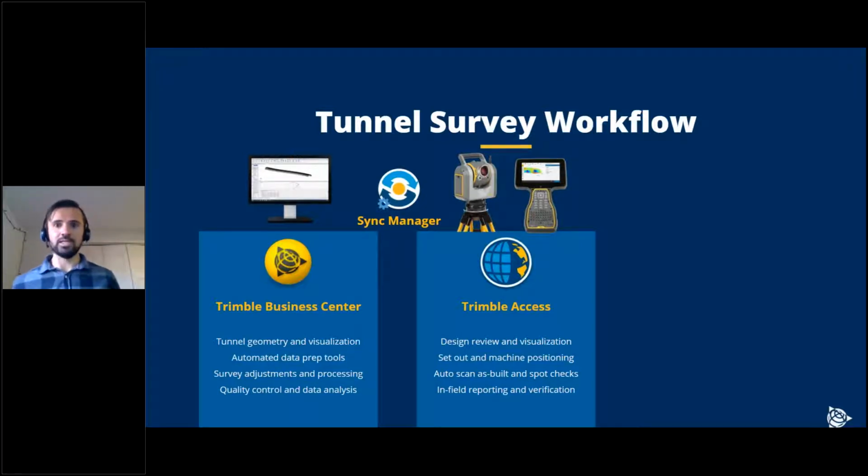I also have all the tools I need to do any of the set out and positioning. So whether I'm setting out blast holes, whether I'm setting out rock anchors, whatever it might be, you can do that in Trimble Access. There's also some basic machine positioning functions. So if I need to direct a road header, I need to give them kind of the extents with the laser pointer, I can use the alignment and the design information to position that with Trimble Access.